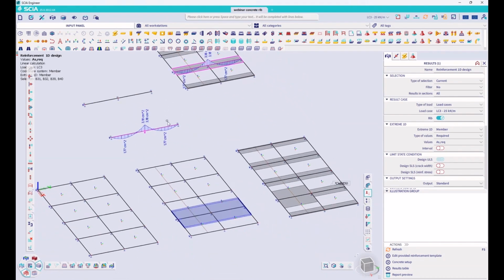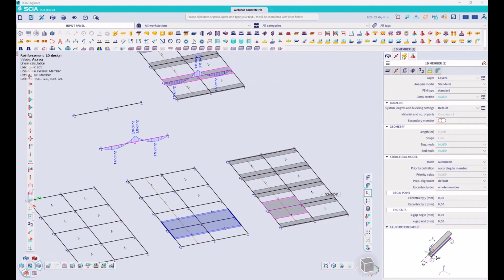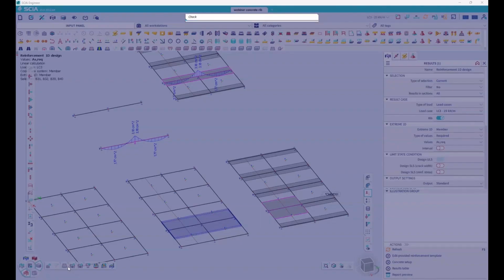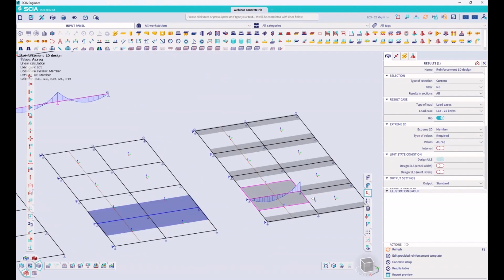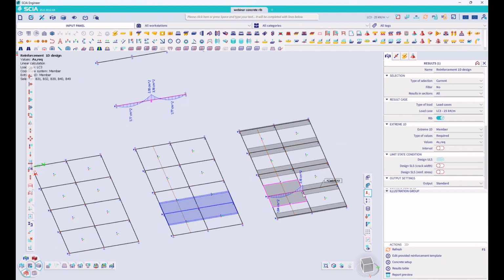If I compare that with the concrete rib where I took into account all of the forces as well, but I took them over a zone of 5 meters while it recalculated, or it's calculating the reinforcement for this section with a width of 2 meters, you can see that it also closely resembles this value, but it's not completely the same. And that is, like I said before, also due to the fact that the center of gravity is slightly different between these two models.